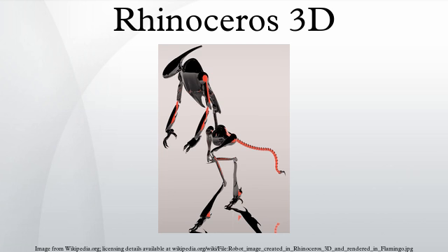When Autodesk AutoCAD's file format changes, the Open Design Alliance reverse engineers the file format to allow these files to be loaded by other vendors' software. Rhinoceros import and export modules are actually plugins so they can be easily updated via a service release. Rhinoceros service releases are frequent and freely downloadable. Rhinoceros 5 can import and export DWG-DXF file formats up to version 2014.